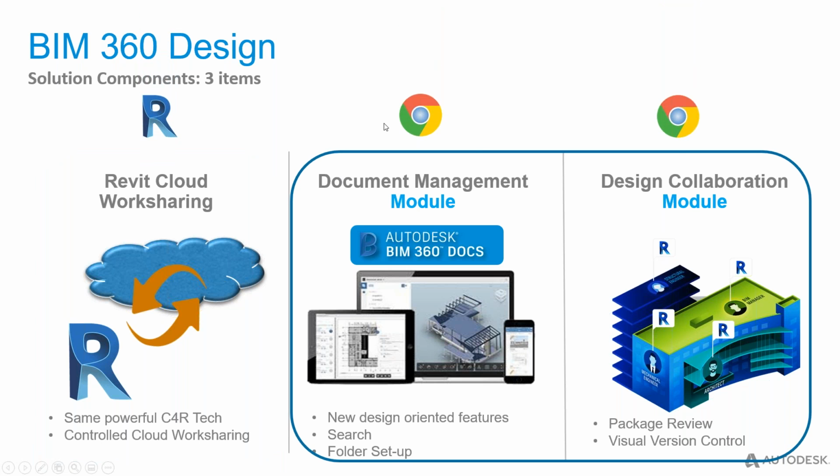So you'll see this one sits in Revit. These two are cloud-based. This is the actual BIM 360 Design module in the cloud. I'll give you a screenshot later on. This is the official handover project through what we call packages between the different disciplines. So as I mentioned, yes, the technology is still Revit work sharing, but there's a lot more to it to get to that official handover process between different disciplines.